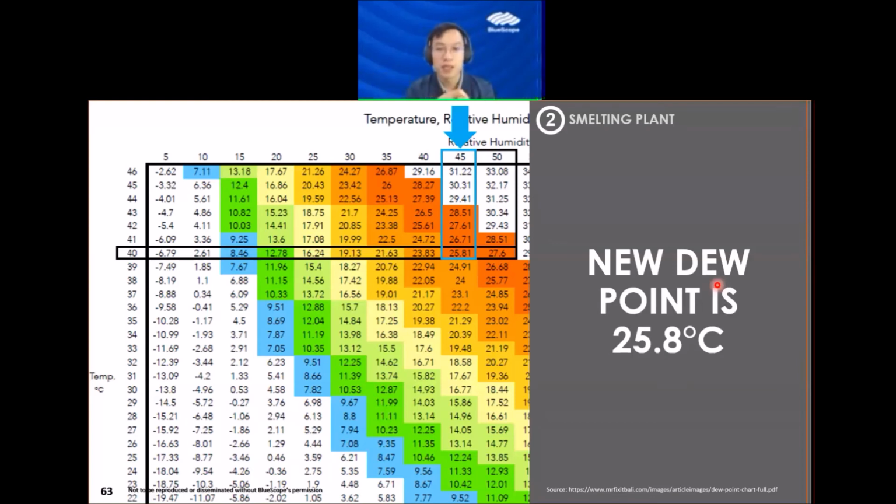Okay, so first it needs to be non-permeable, meaning water would not go through this paint to react with the metals, regardless of what kind of metal you have as a roofing. Some of the possible solutions, I think for the building I-beams, normally they use epoxy paint, right? So possibly along that line, or epoxy or sometimes PU. But again, you need to clarify with the paint supplier whether it is able to be non-permeable, or whether it can even resist the high temperature it is exposed to, right?